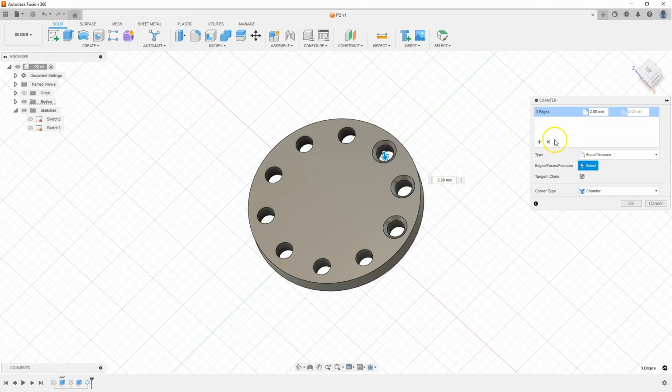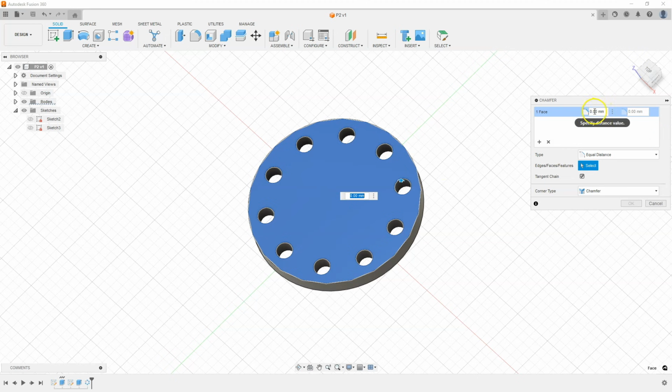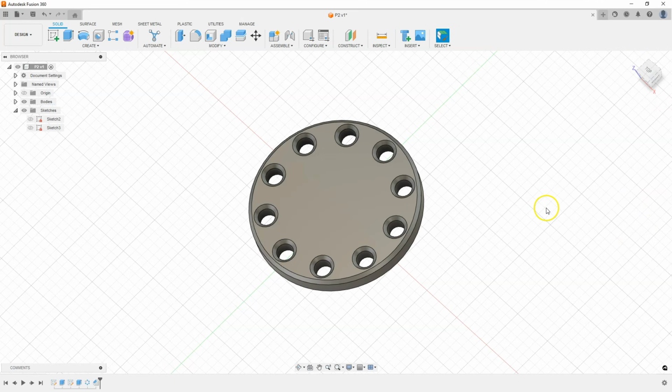In a similar way, we can add chamfers to all edges of the selected face. Then instead of an edge, select a face and set the chamfer size. And as you can see, adding chamfers and fillets is very simple, and these are very useful operations. Chamfers and roundings often improve the functionality of the finished part made on the basis of a designed 3D model.